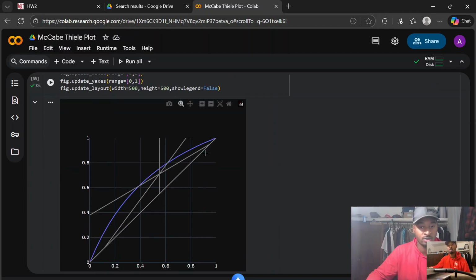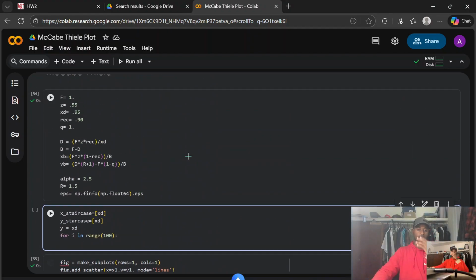So as of right now, we know what xd is, and by knowing that, we are able to translate what y1 would be. Now the problem is we don't know what x1 would be. So we need to be able to formulate an equation to figure out what that is. And we can do that with the equation we utilize to find the vapor mole fraction given a liquid mole fraction and our alpha term, 2.5. This time we'll just be doing that in reverse to find what that liquid mole fraction will be given our y mole fraction and our alpha term.